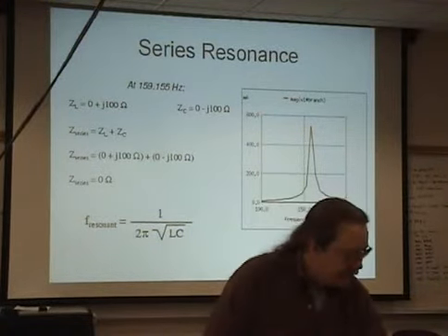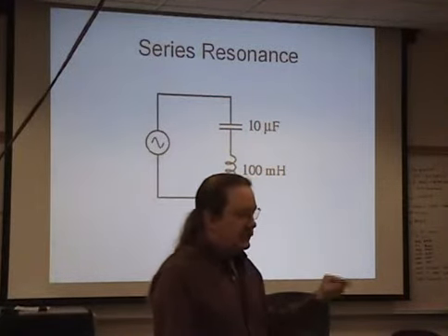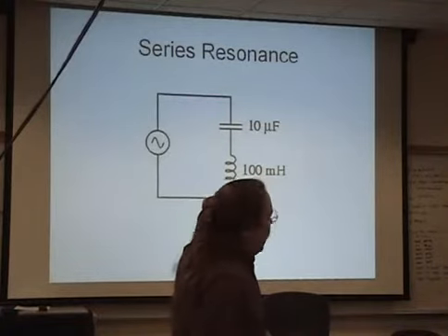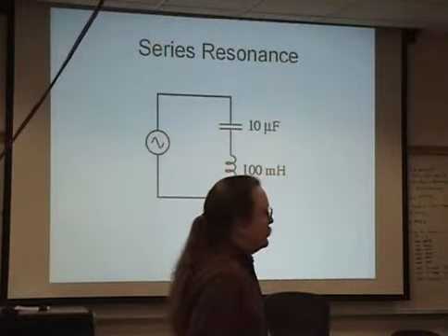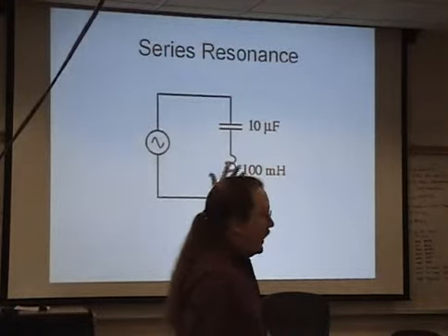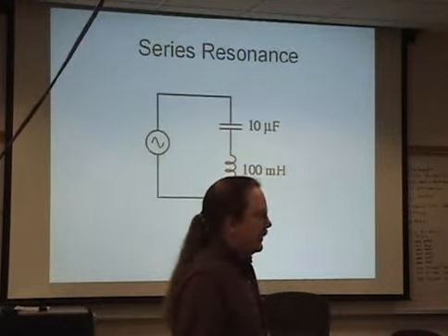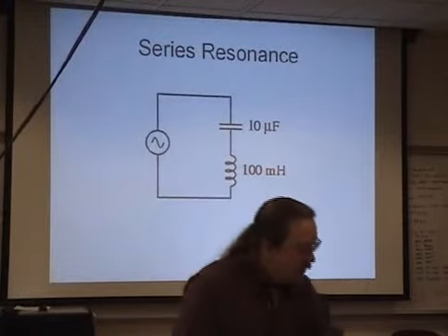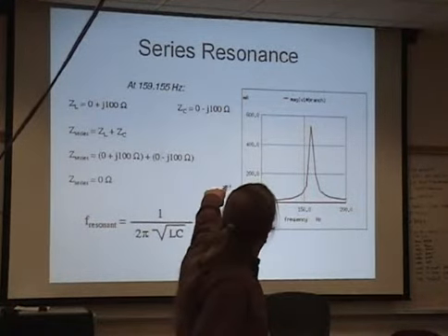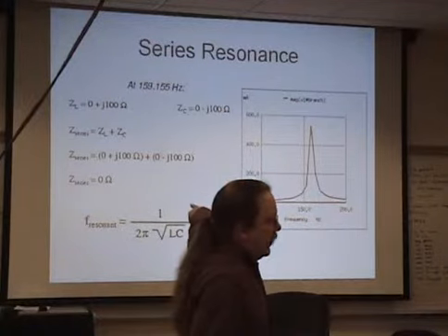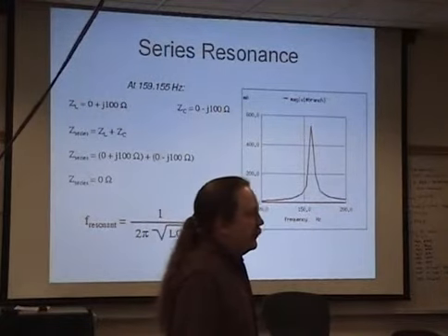Now we're getting to the new stuff. Radiation patterns is what we're going to be talking about a lot. The radiation pattern of various antennas shows you when you might want to use one antenna over another, how you can modify something in the field, so why you might want to use your quarter wave vertical upside down. Say you're on a mountaintop and you want to talk to somebody down there. If you did this, you're not going to talk to them. They'll be able to talk to you, but you can't talk to them unless you do this. I'll show you why when we get to the quarter wave vertical. It has to do with its radiation pattern and takeoff angle.